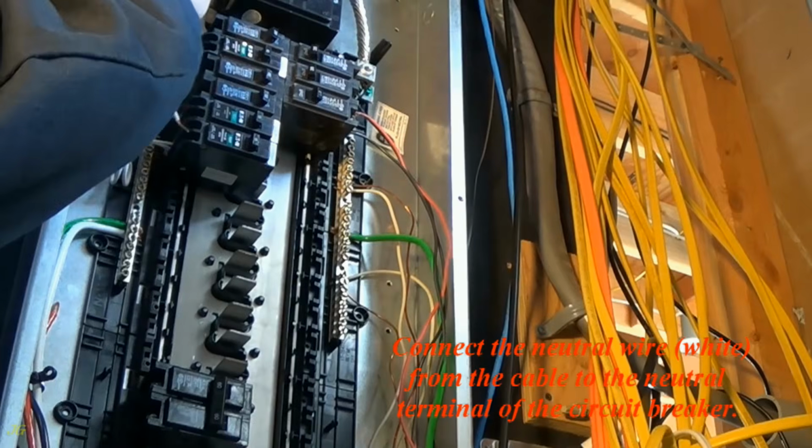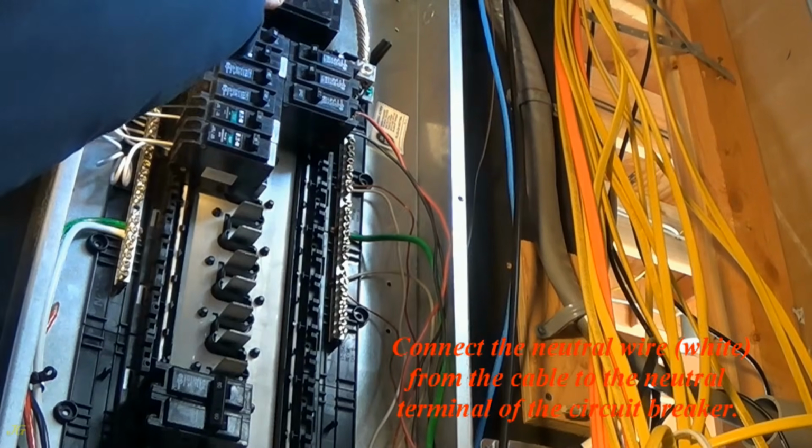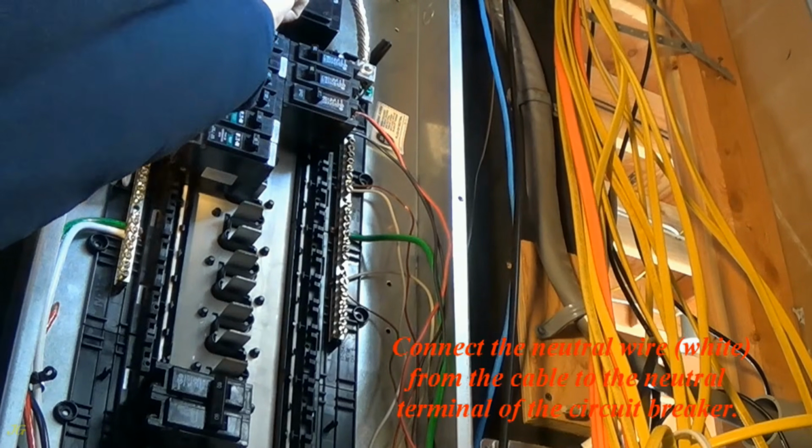Connect the neutral wire, white, from the cable to the neutral terminal of the circuit breaker.